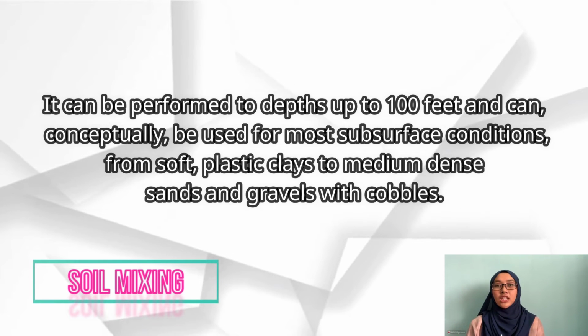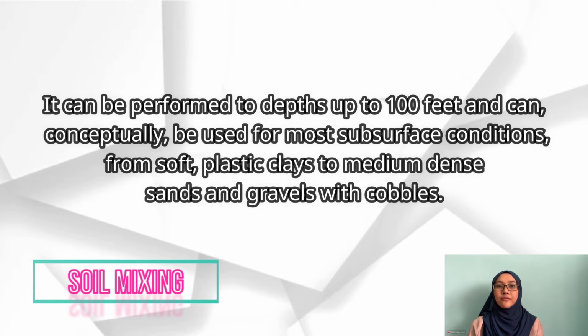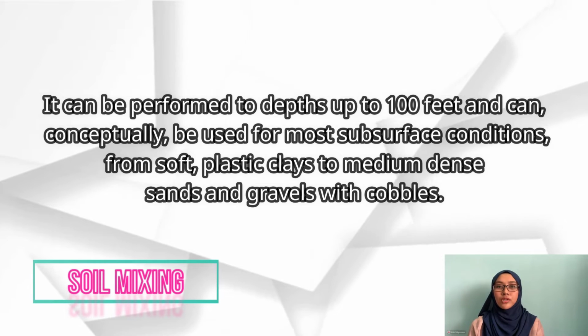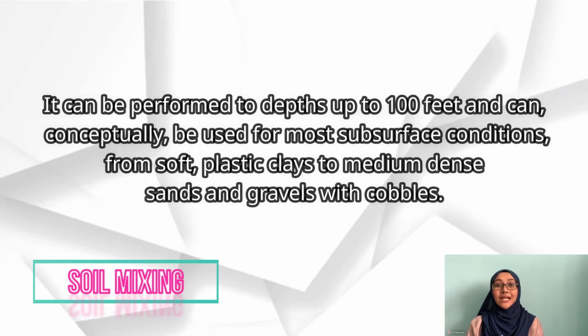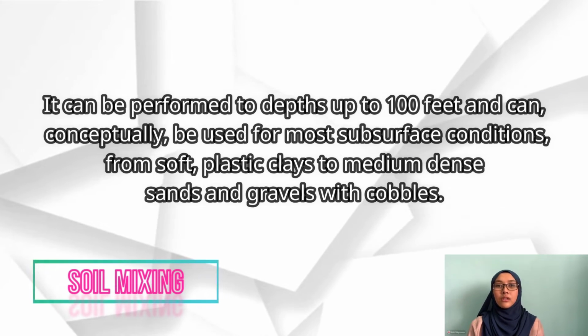First, soil mixing can be performed to depths up to 100 feet and can conceptually be used for most subsurface conditions, from soft, plastic clay to medium density sand and gravel with cobbles.